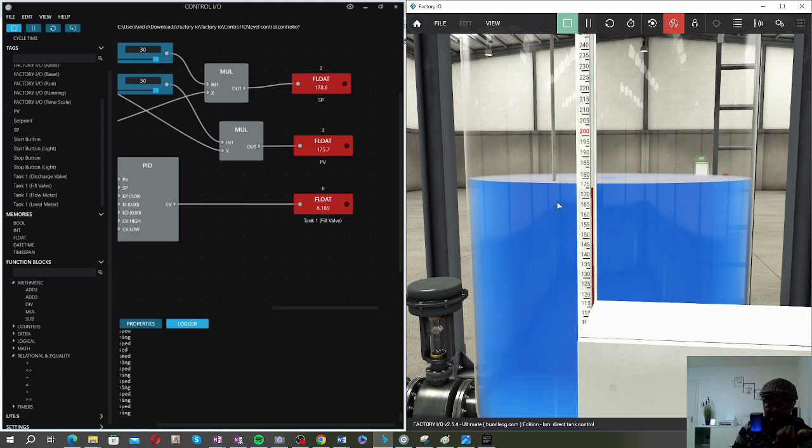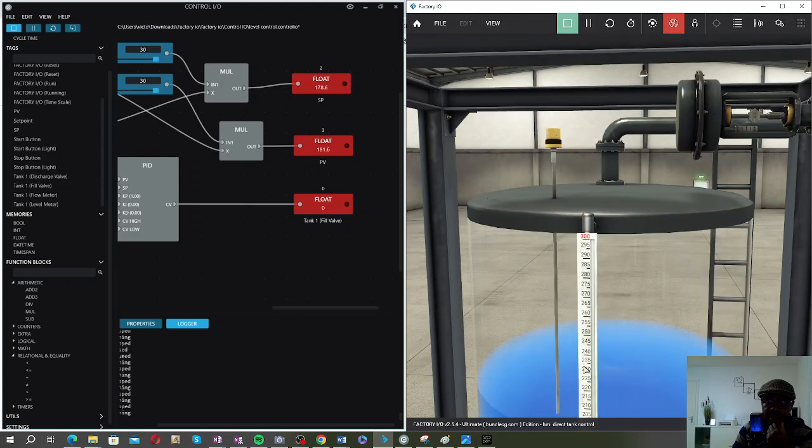The response, as in how fast your controllers respond. There's going to be some delay, some lag, and this can affect all that. The thing is that you don't want it to be too exact, because if it's too exact, any little fluctuation will trigger it. If you look at this now, you see it's opening and closing. Now it's closed because the tank is emptying.